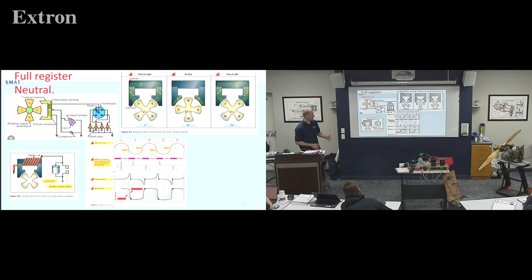So what we did is install a capacitor in there, so that when we open the points, instead of sparking across them every time, it draws a bunch of electrons from one half of the capacitor to the other half. And I can see your brain, Micah, because mine does the same thing, going, wait, does that even open the points then?